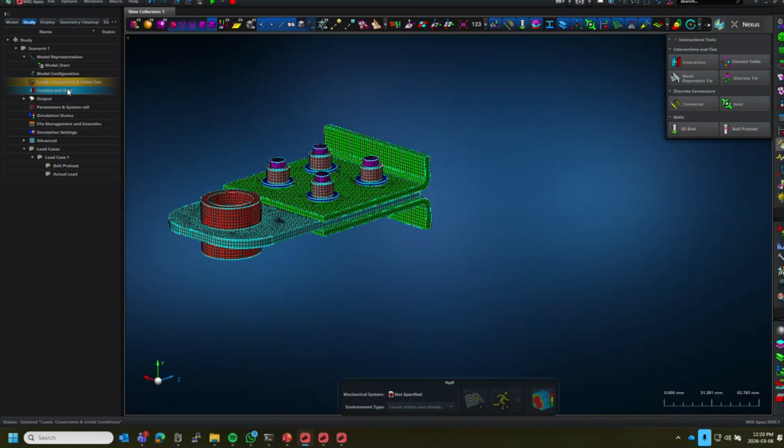Nothing special there. I want to get back to contact because that's what the session is about. Let's fill in the rest of the things that are pretty general in terms of Nastran things that you need to set up, especially for SOL 400. Now, the same occurs for SOL 101, in other words, linear static. If you do a contact analysis, there's one or two settings that are also new there that you don't usually do.